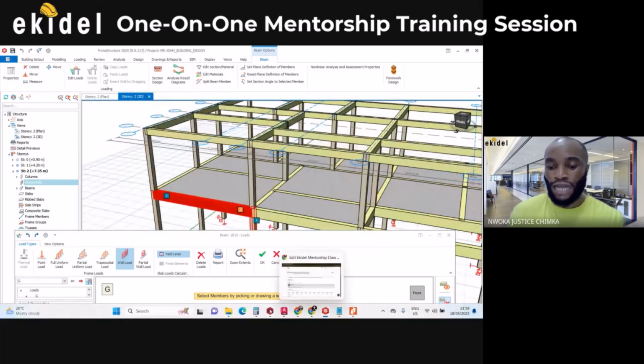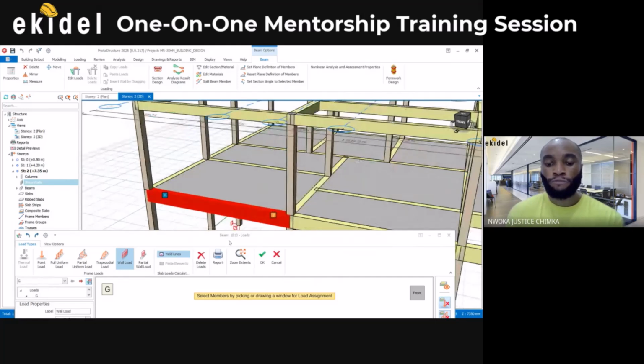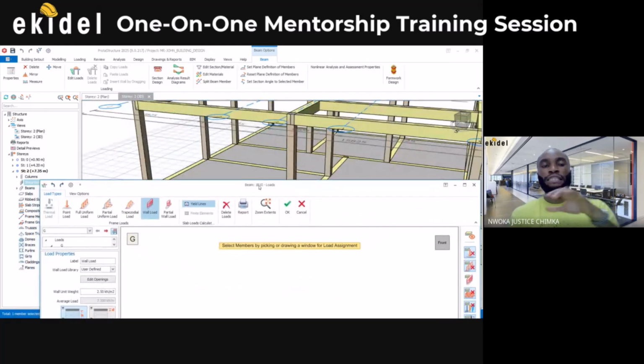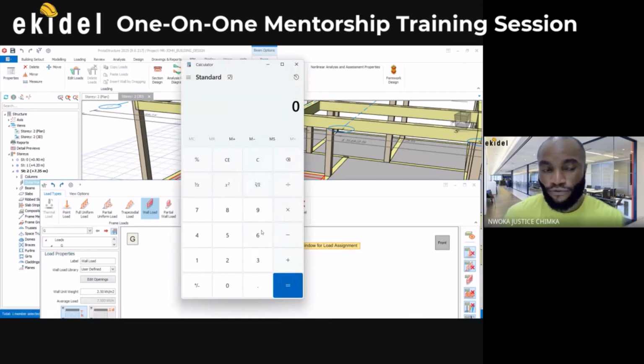So we subtract 3.15 minus this beam depth, because right now we are trying to give the actual space the block will occupy, which will be under the beam surface of the roof beam to the top of the slab. So we subtract the height of the story, which is 3150, minus 300, which is the beam depth. So this is the actual space that the block will occupy. I don't know if you understand what I mean.